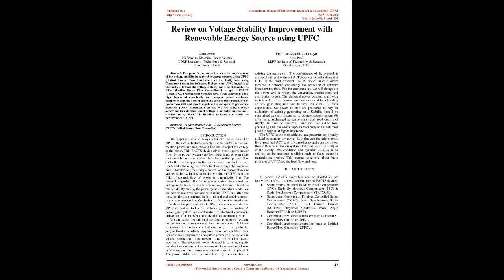If there is no UPFC installed at the faulty side, then the voltage stability can't be obtained. The UPFC, Unified Power Flow Controller, is a type of FACTS, flexible AC transmission systems, device that is developed with a high degree of complexity and complex power electronic equipment, and has been developed for the control and optimization of power flow, and also to regulate the voltage in high voltage electrical power transmission systems.